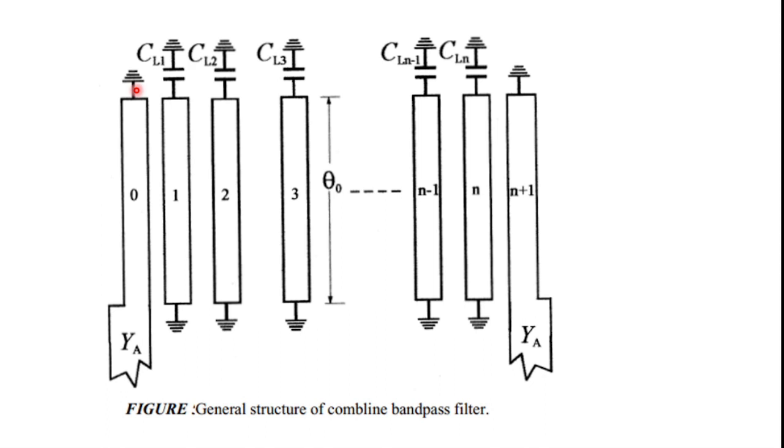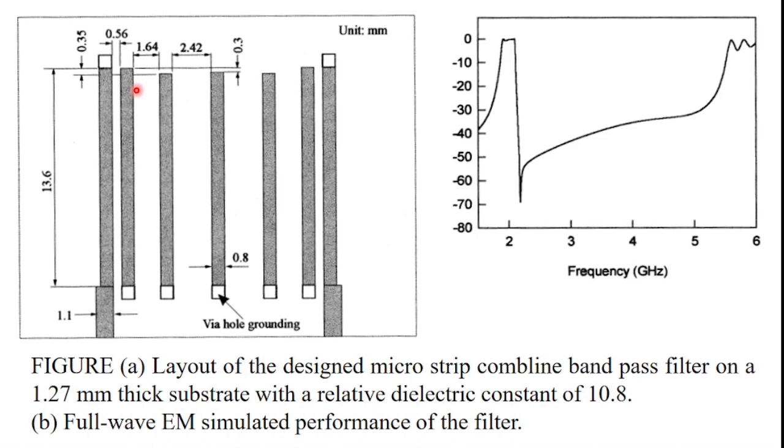In this design, the microstrip filter is designed on a commercial substrate. Here I am considering the material Rogers RT Duroid 6010, with a dielectric constant of 10.2 and a substrate thickness of 1.27 mm. This is the layout of a microstrip Combline bandpass filter. Now open HFSS software.